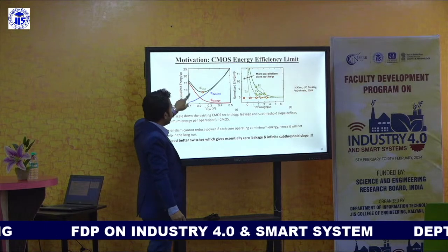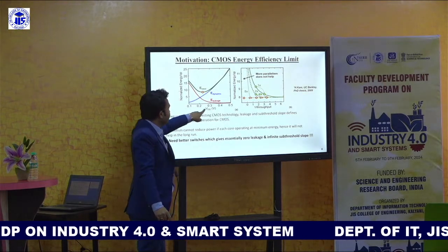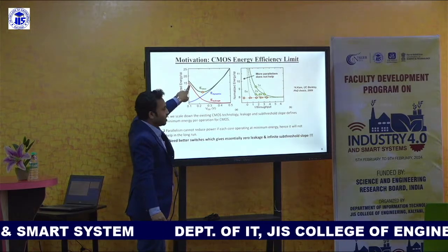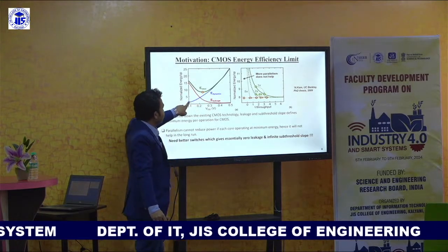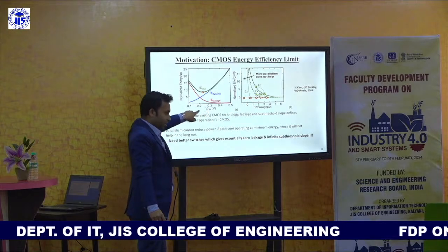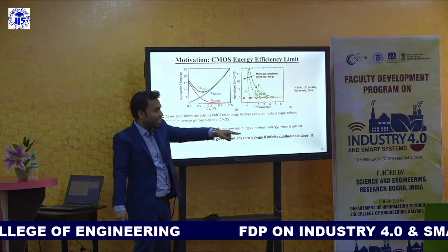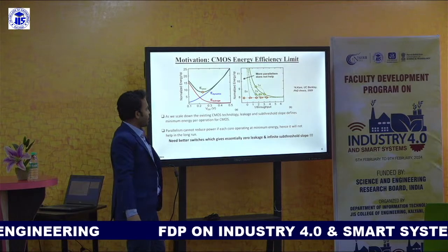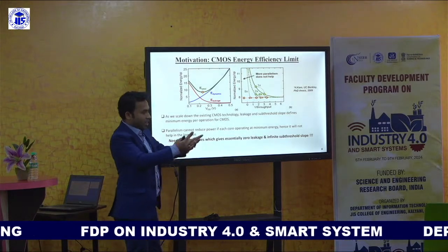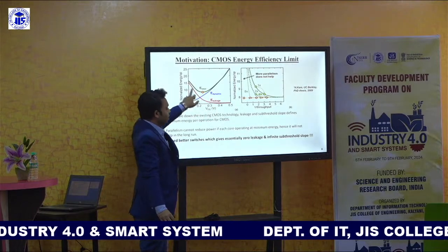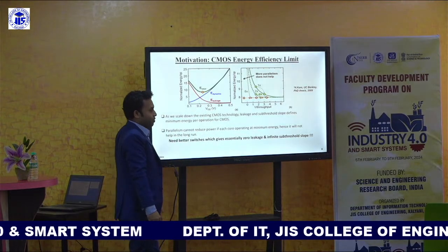That's why nowadays, if you reduce the VDD, your leakage current keeps on increasing. Even though your dynamic power is decreasing, because you are reducing VDD, your leakage keeps on increasing, and because of that this is happening. If you uninstall everything, because of this one, it will still reduce your battery life.